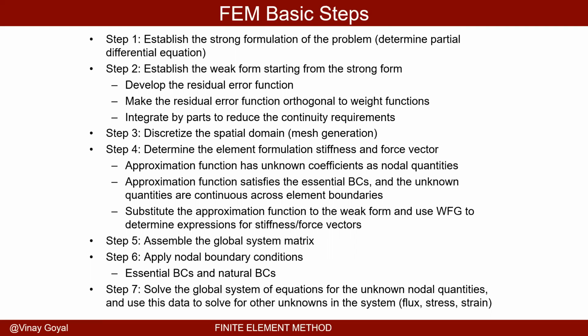Step number three is to take the domain that we have of interest, could be the aircraft, whatever it is, and we want to divide that domain into elements. And we're calling that the mesh generation portion. So I have this domain, 3D or 2D, and the idea is to break up that domain into subdomains called elements. And what we want to do is break it down into subdomains where the elements are similar to each other in geometry, for example. And I'll show later how to approach it.